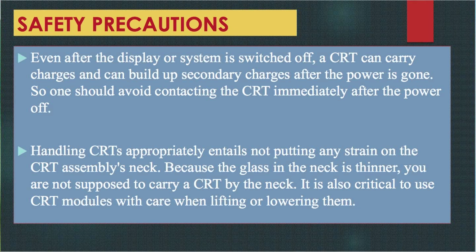Next point, handling CRTs appropriately entails not putting any strain on the CRT assembly's neck, because the glass in the neck is thinner and you are not supposed to carry a CRT by its neck. It is also crucial to use CRT modules with care when lifting or lowering them.